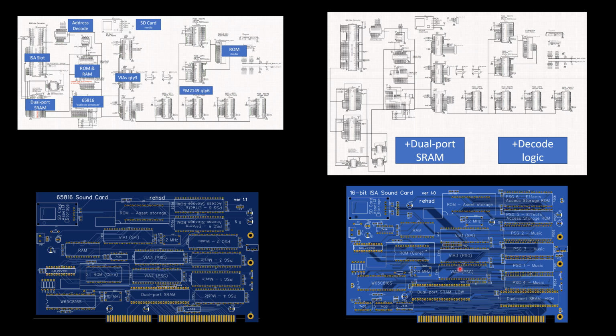I have 3 VIAs that are going to help control those sound generators, along with giving me access to my SD card, and a couple of debug ports that I can use, for example, for a 2-line LCD for debugging this sound card, which is essentially a full system on its own. It has a processor, it has the ROM, it has the RAM, it has a VIA. I can plug in an LCD and really do everything I need to. And even if I think about my 286 system, the keyboard, mouse, and all of that, I've moved over to SPI.